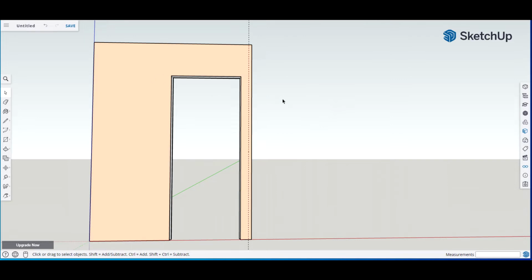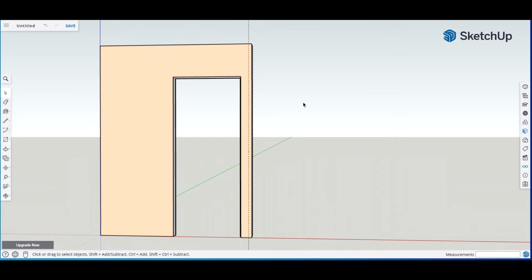Also, we're going to create some miters. So let's go ahead and do that. I'll show you how to do that right now. We're going to do the door molding on the outside here. And the reason why is if we do it on here, create the thickness, it will pick up this color. I want to rest it on top because it's a different component. And as you notice, I have not created a component yet on this whole thing, and I won't do that till I get the whole wall done.